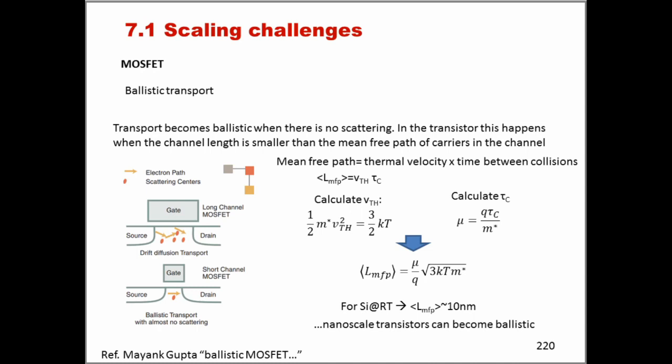It is only when this piece of material becomes small enough that scattering at a certain point may cease to happen. When the distance charges need to travel is smaller than the mean free path of our charge carriers, we may not see any scattering phenomena anymore. And so in this situation, we will say that we are in a ballistic regime.